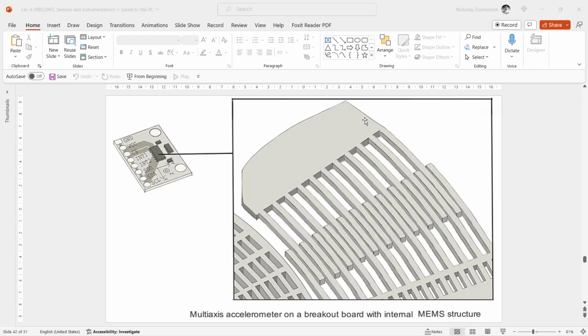Using the circular multiplate capacitor, angular position and angular speed can be determined with high accuracy, as has been demonstrated in many research papers. With a careful design, an angular position sensor can have a resolution of 18 bit and reproducibility of 17 bit and an absolute accuracy better than 14 bit. A micro machined contact-free angle sensor.